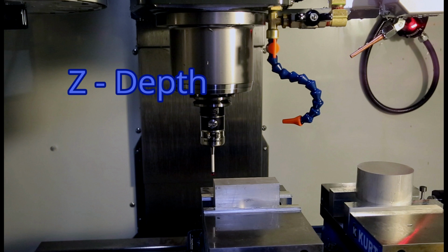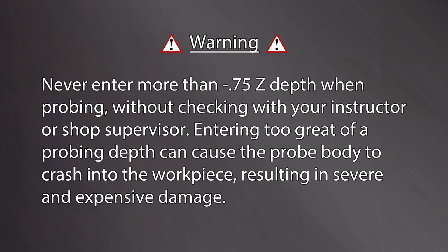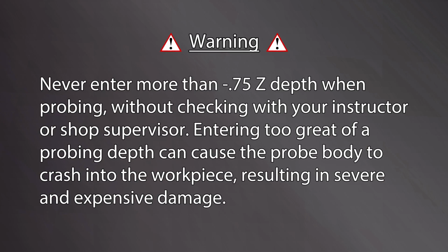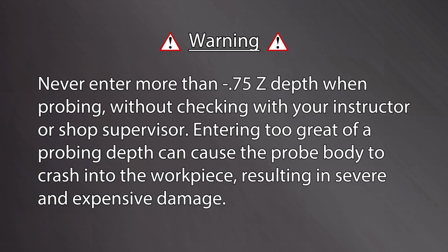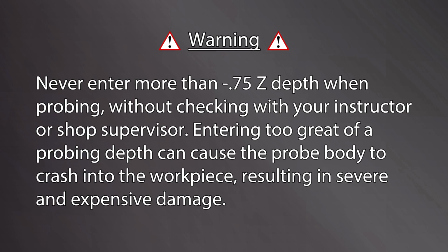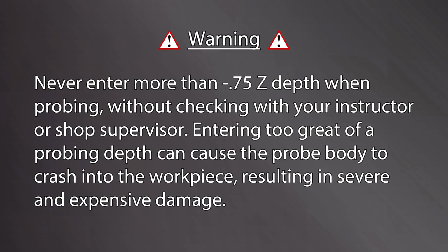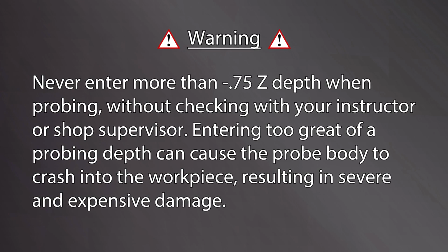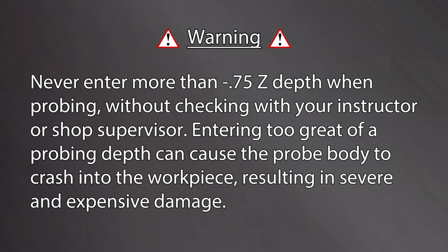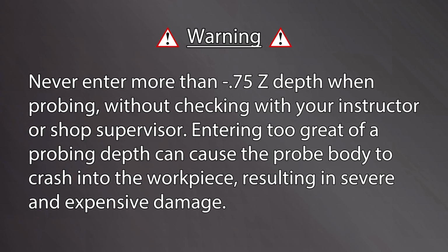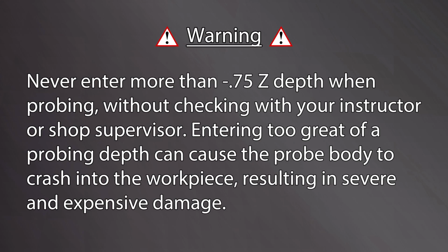For Z-depth, this is not the depth of the workpiece. Rather, this is how far down the probe will move. Never enter more than -0.75 Z-depth when probing without checking with your instructor or shop supervisor. Entering too great of a probing depth can cause the probe body to crash into the workpiece, resulting in severe and expensive damage to the probe.